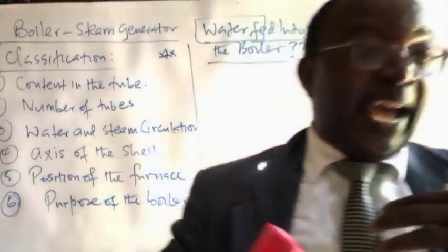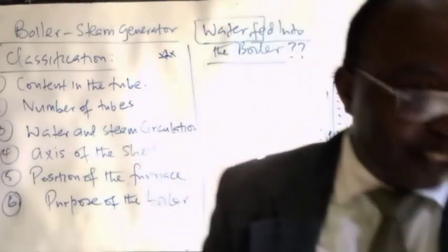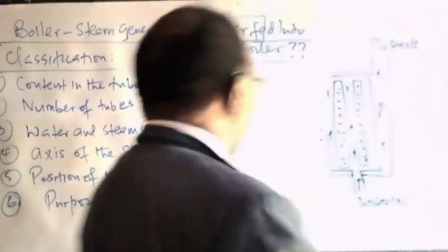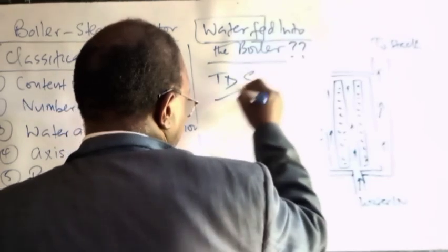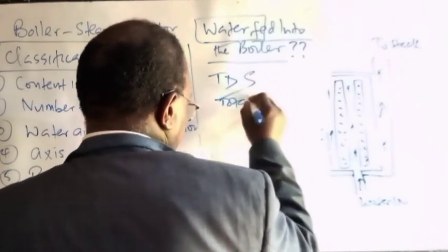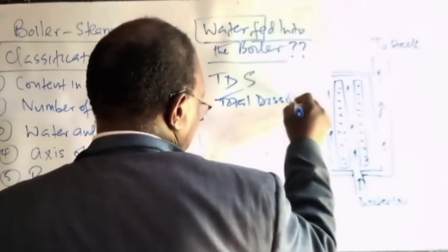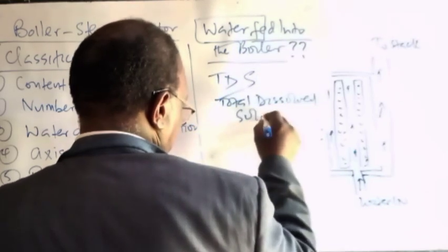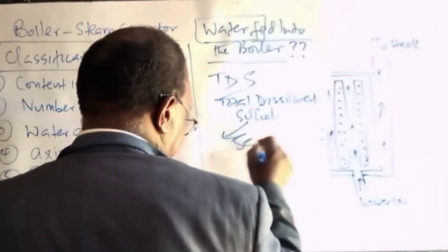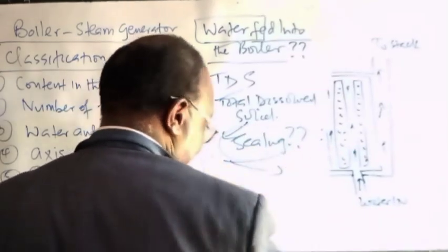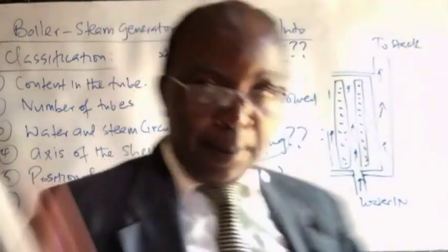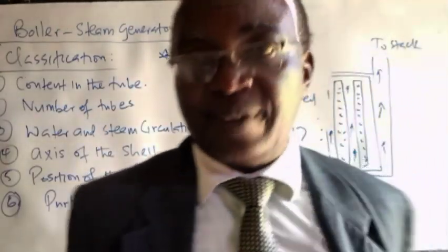In other words, an insulator, so that heat is not transferred across the walls. So you need to worry about the level of purity of your water. This is total dissolved solids. If you don't do that, you can be dealing with very serious cases of scaling and have to make your system insulating or adiabatic, in quotes. No heat transfer across the wall.